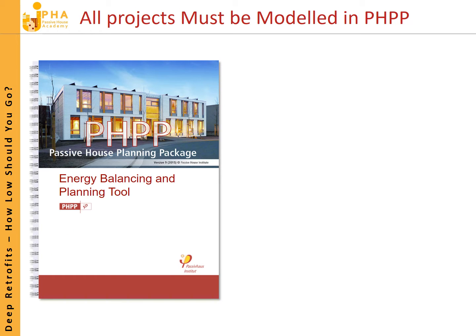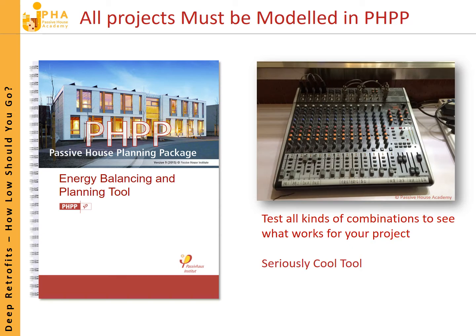Despite all those components and standards, we must model every project in the Passivhaus Planning Package, and the PHPP is a bit like a sound desk where you've got levers for insulation, for window performance, for ERV efficiency, and the objective is to use the PHPP as a design tool to hit the sweet spot for your retrofit project.